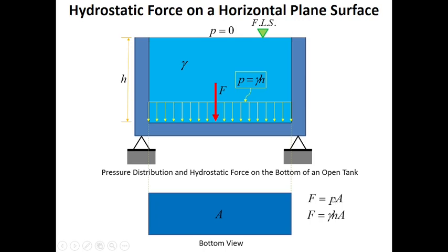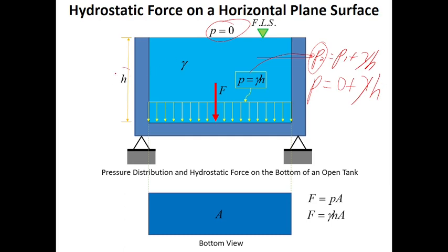And the pressure is simply equal to the specific weight of the liquid multiplied by the pressure head H. Actually, this was derived from P2 equals P1 plus unit weight times H, the formula I showed before. For the bottom we have P, and for the top, the gauge pressure is 0, plus the unit weight of the liquid times the pressure head, or the height.